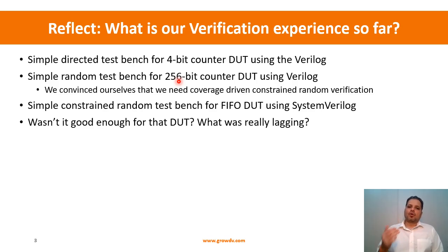And then we moved on to SystemVerilog, and we took a slightly more complex DUT, a synchronous FIFO DUT. We applied how we can structure coverage driven constrained random verification, and we were able to solve the verification problem using SystemVerilog constructs, and we understood to some extent what benefits it provided.